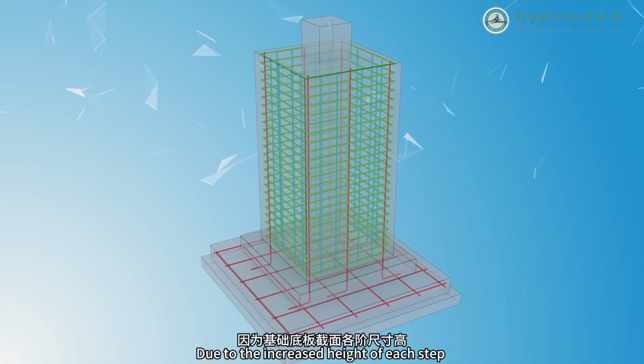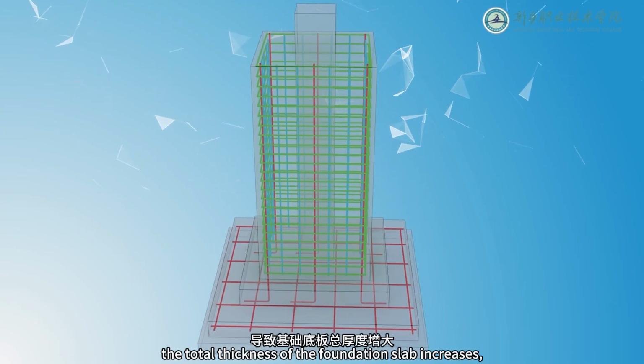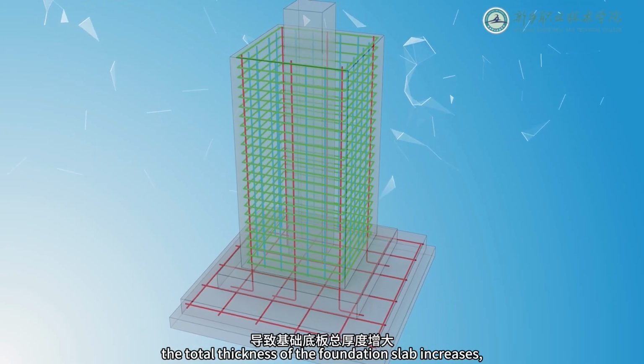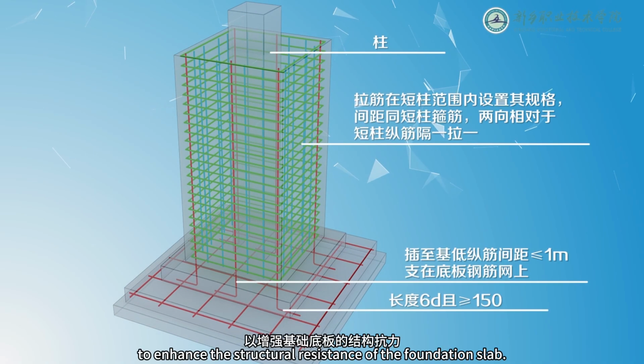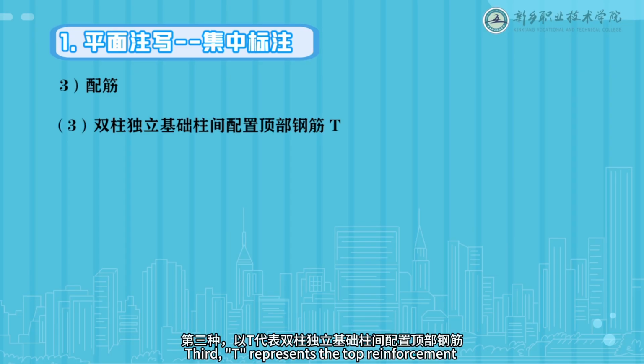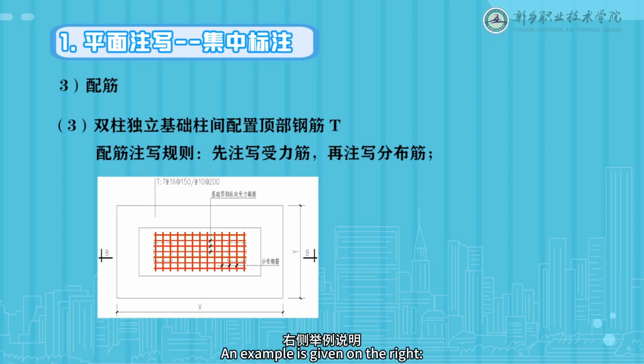Due to the increased height of each step in the cross-sectional dimensions of the foundation slab, the total thickness of the foundation slab increases, so short reinforcing columns need to be added to enhance the structural resistance of the foundation slab. Third, T represents the top reinforcement arranged between columns in double column isolated foundations. Reinforcement annotation rules. First, annotate the tensile reinforcement, then the distribution reinforcement. An example is given on the right.